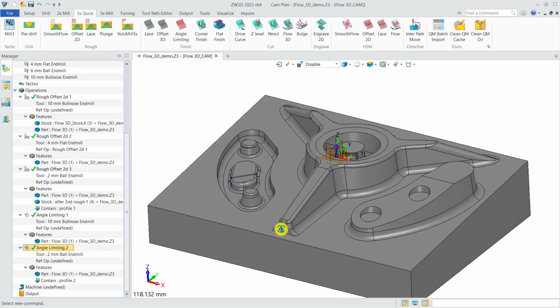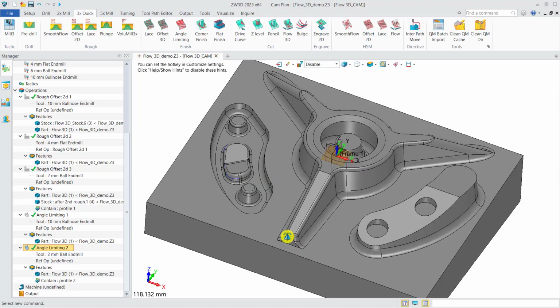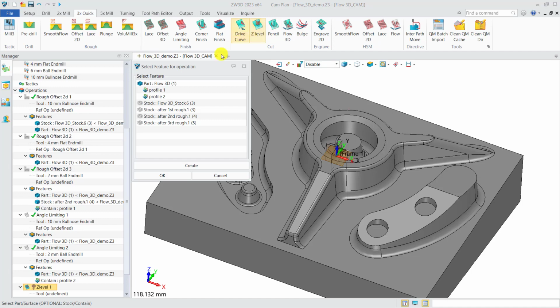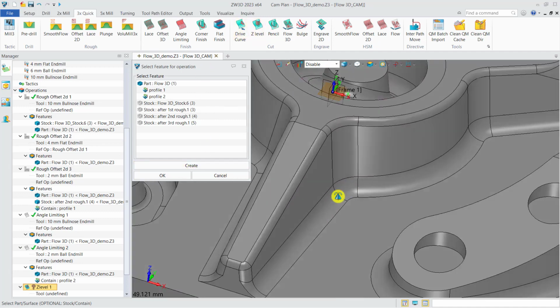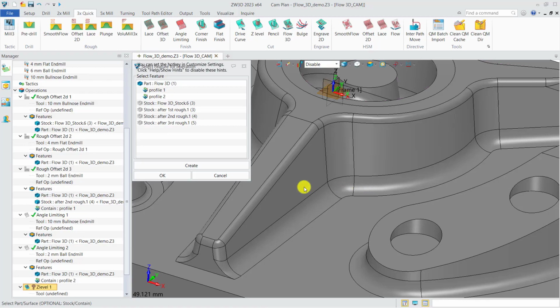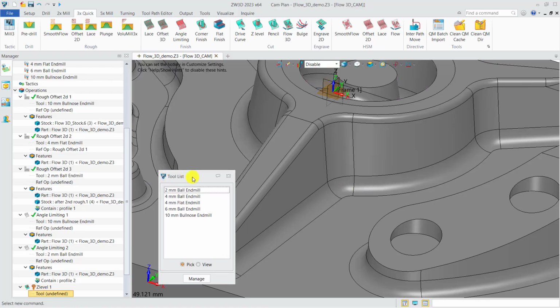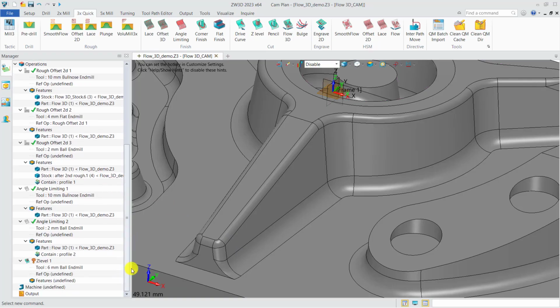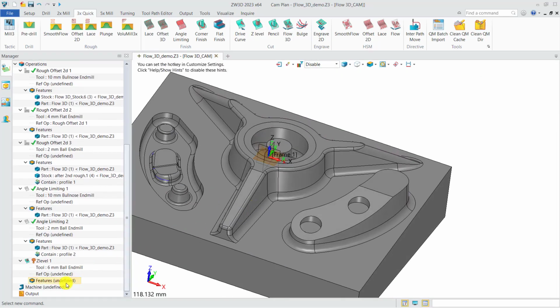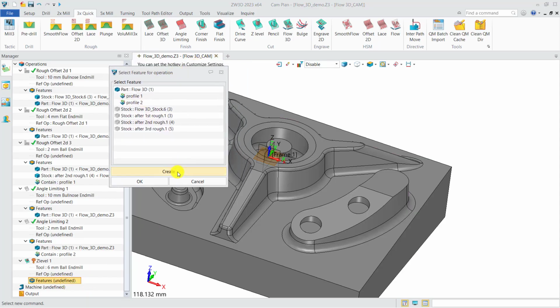To ensure the surface quality, we need to process by regions. We will start from the middle section. For this vertical surface, it's better to use J level. And based on the previous analysis, the radius here is 3.5 mm. So we use a 6 mm ball end mill. Okay, then we select the outer profile and one of the inside circles as the feature.